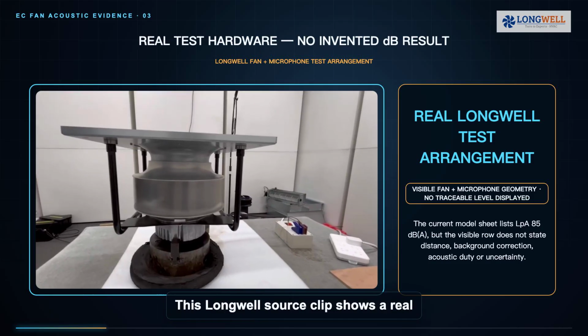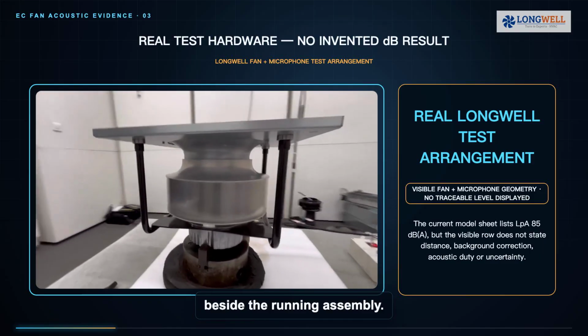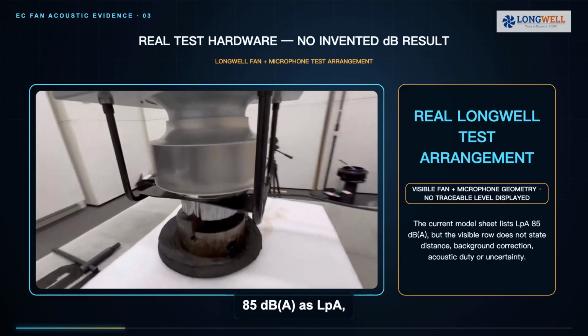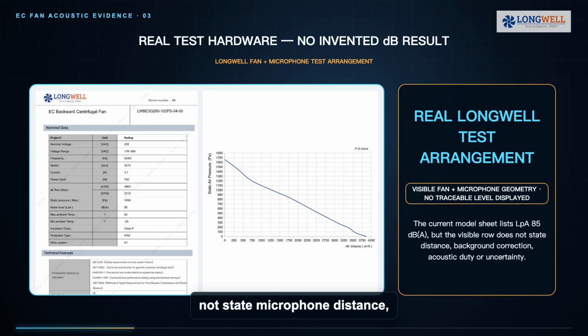This Longwell source clip shows a real fan test arrangement with a microphone beside the running assembly. The current exact model sheet lists 85 dB, A, as LPA, but its visible nominal data row does not state microphone distance, background correction, the acoustic operating point, or uncertainty. The clip itself shows no traceable meter result. These are useful pieces of model and geometry evidence, not a universal comparison by themselves.